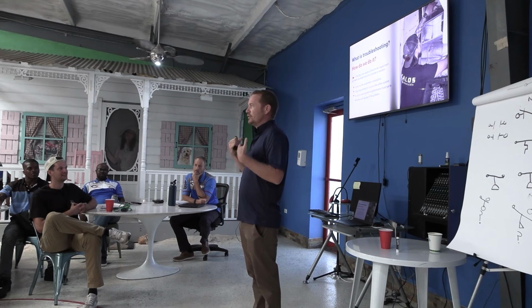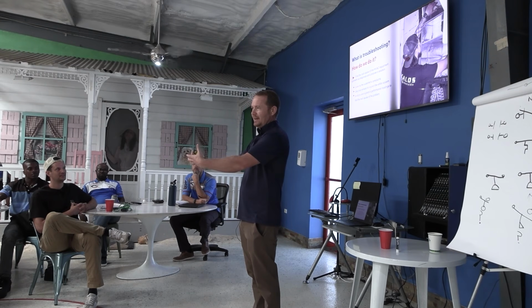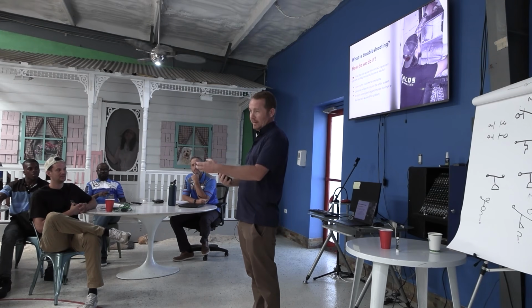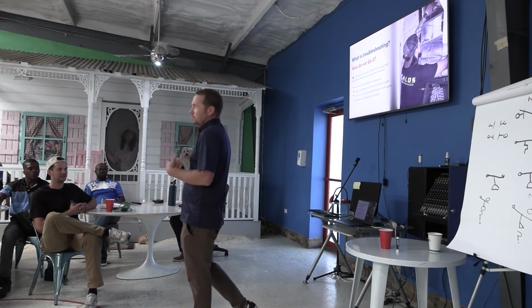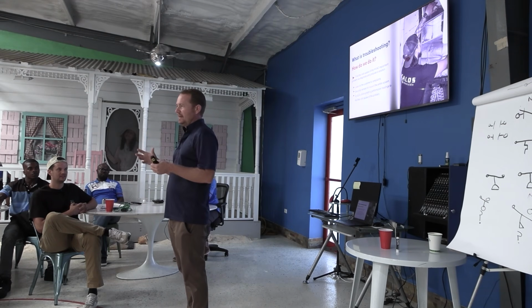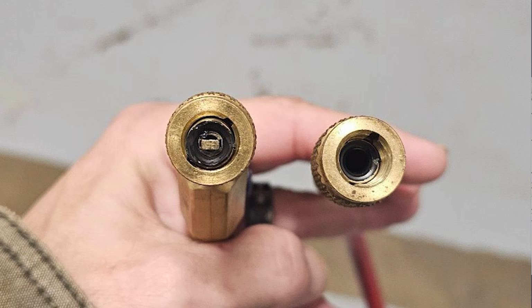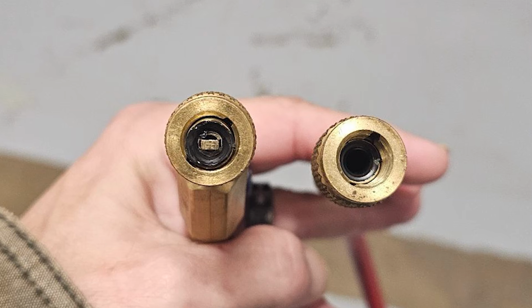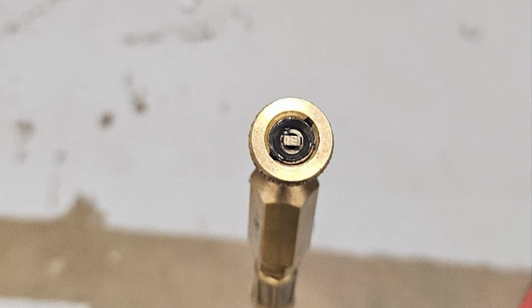The problem is that you're not committed to gathering data and process elimination. And I can tell you that particular call I've received probably 50 times over the years, and it's a version of that, and it's literally because they either have the hose hooked up backwards, so that way the Schrader's not being depressed because there's no core depressor on the one side, or it's just not screwed on far enough, so it's not pushing the core in.